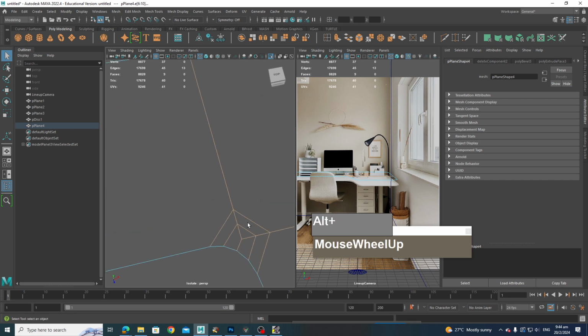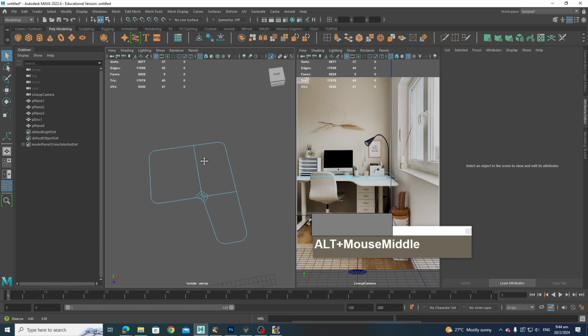Okay, unfortunately, when I press Ctrl Delete, these vertices here will also be removed. So I want to keep these edges for now and press Ctrl Delete. Unfortunately, it will still disappear. Okay, never mind. We will just keep this here for now and redo our topology, because we really want to keep the nice curve around here. So we can skip that, go over to vertex, and do our connection.